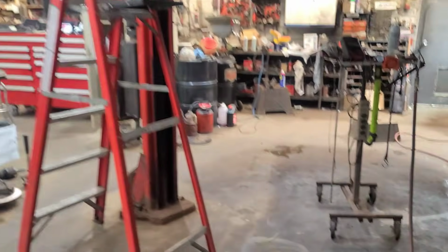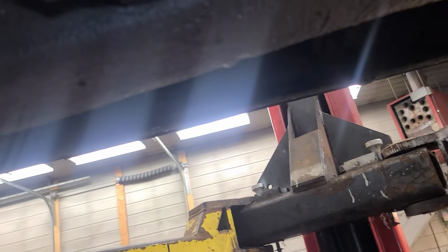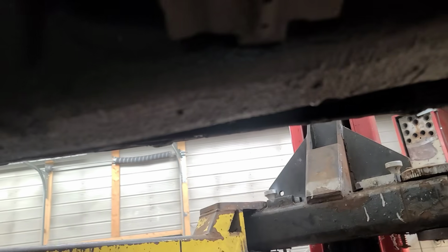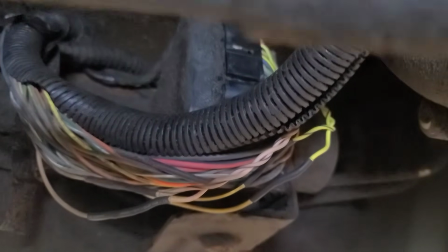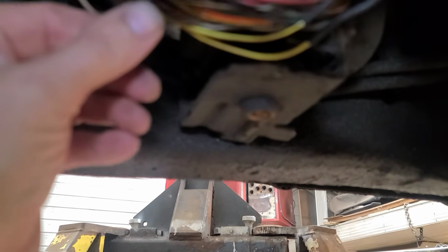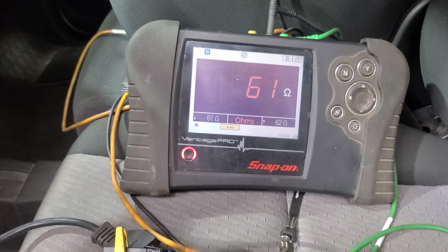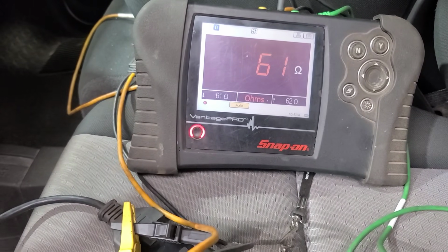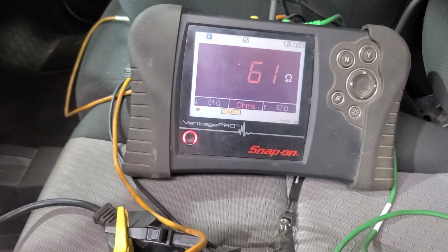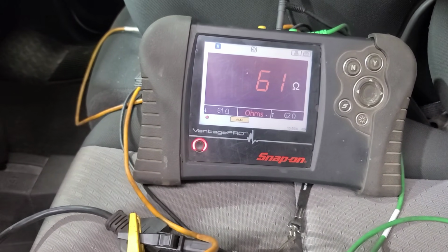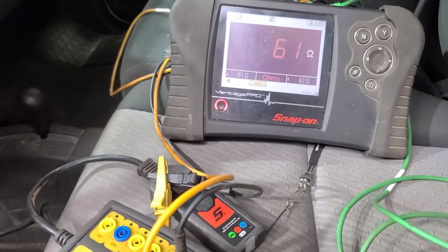I still have to tape up this front harness and see if I can figure out a way to secure that connector on there, maybe with a tie wrap, because the lock is missing. But it measures 61 ohms at the DLC now. So as you can see, measuring across 6 and 14 now at the DLC, we've got 61 ohms. The spec is 60 plus or minus 2 usually. So we're going to reconnect the battery and check the lab scope pattern and do a network scan again.